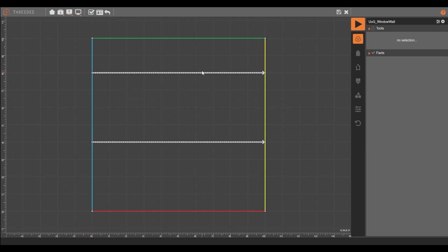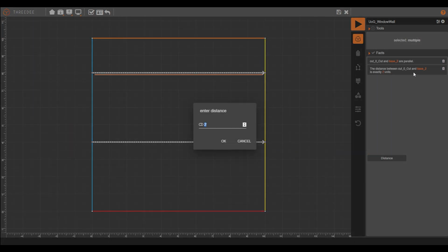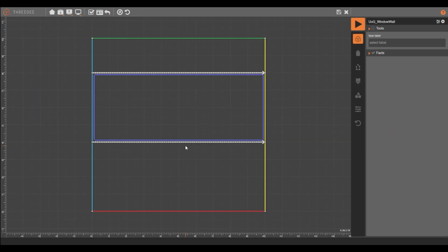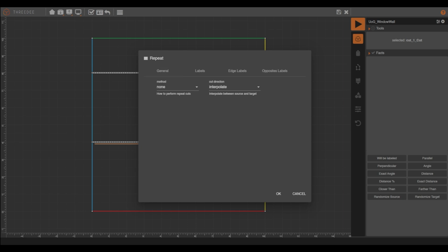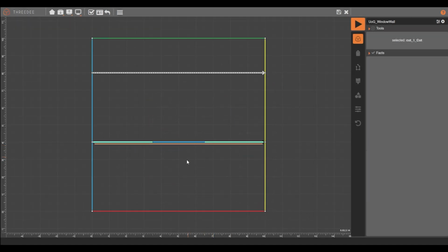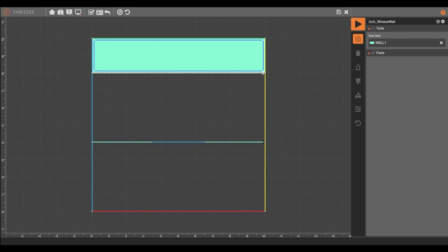We will then create another cut node with 2 cuts from west to east, where cut 0 will be parallel to base 2 and will have an exact length of 0.5 units. Cut 1 will be a cut repeat by length with a distance of 3 units and 1 as maximum cuts. It will be adjusted to the secondary.